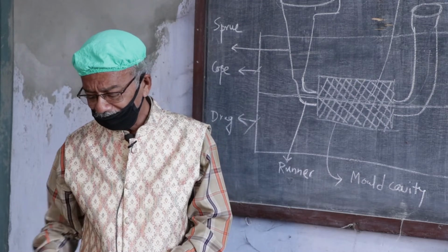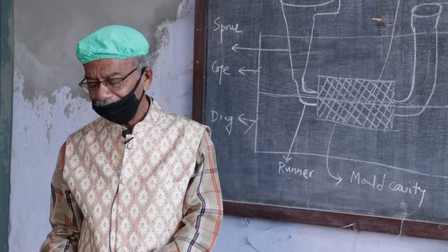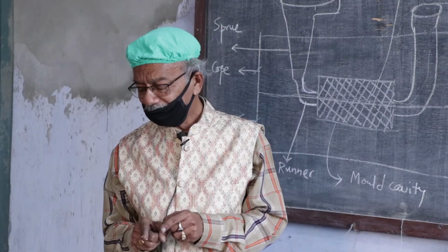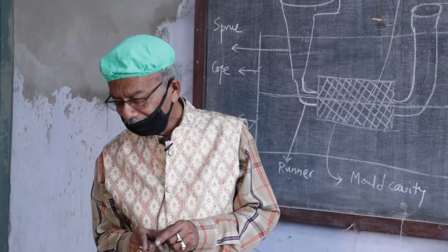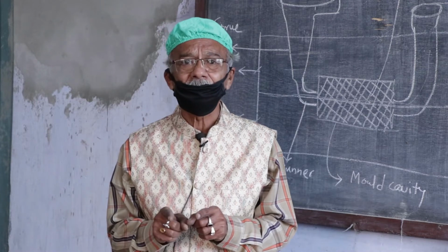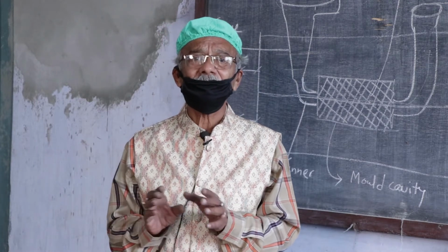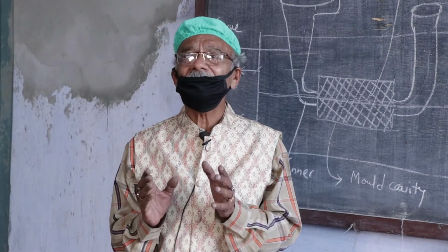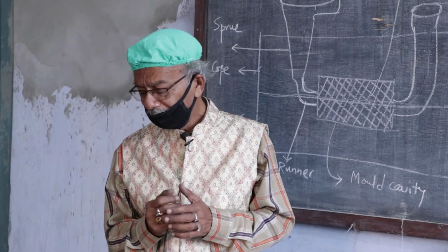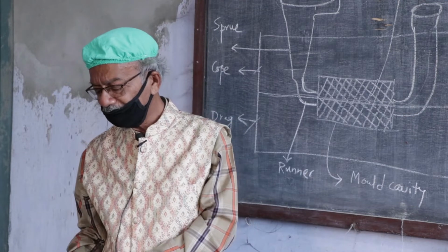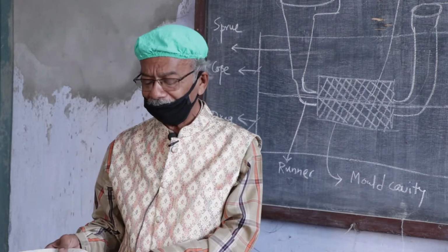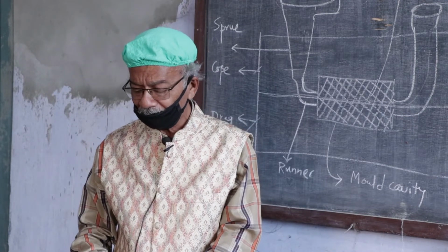After visual inspection, if we cannot find any defect, then go for NDT or non-destructive testing. The first non-destructive test is the pressure test. With the application of some pressure, it is basically used for checking pressure vessels. After that, magnetic particle inspection.